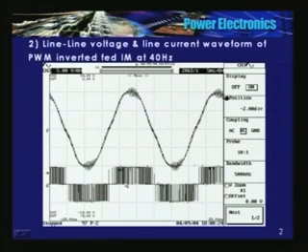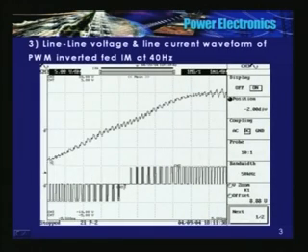See, I extended this waveform. See, it looks like this. See the wave pulses here, large number of pulses. Transition from 0 to the DC link, the rated value is almost instantaneous. In other words, dV by dt is very high. Plus dV by dt as well as minus dV by dt is high. See the current waveform is almost a sinusoid.